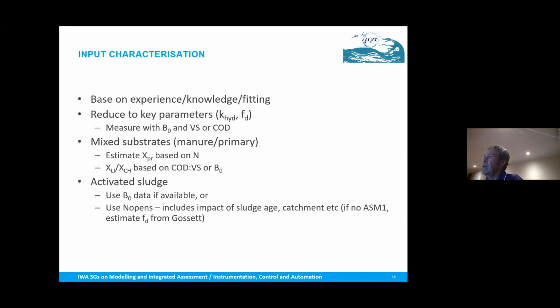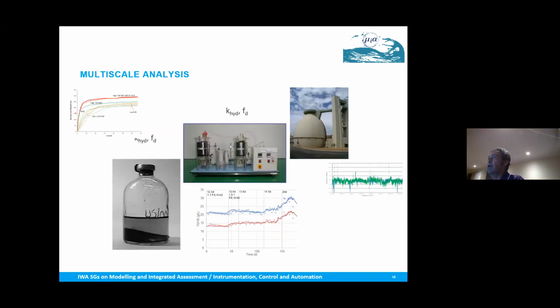You have to then estimate the rates. And we can do that in two ways. We can either do an anaerobic batch test, and if this moves up rapidly, we can fit the parameters, the degradability and the carbohydrate protein lipid ratio, based on the methane response during the batch. It's normally a bit conservative, but realistic. Or we can fit it based on continuous data using parameter estimation.